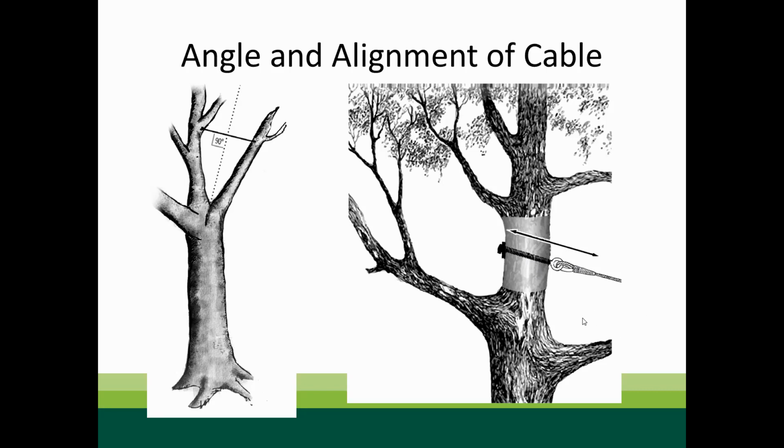So a trick I've used before, and we should maybe get into this: take a laser pointer, tape it to the top of your drill, facing backwards. You can sight down to where your anchor point is going to be then. That's probably some of the hardest part if you're doing long spans, trying to drill and look behind you to see if your drill line is in line with what you're going to be drilling to. So you do your first one, and then you sight your second one in line with that.